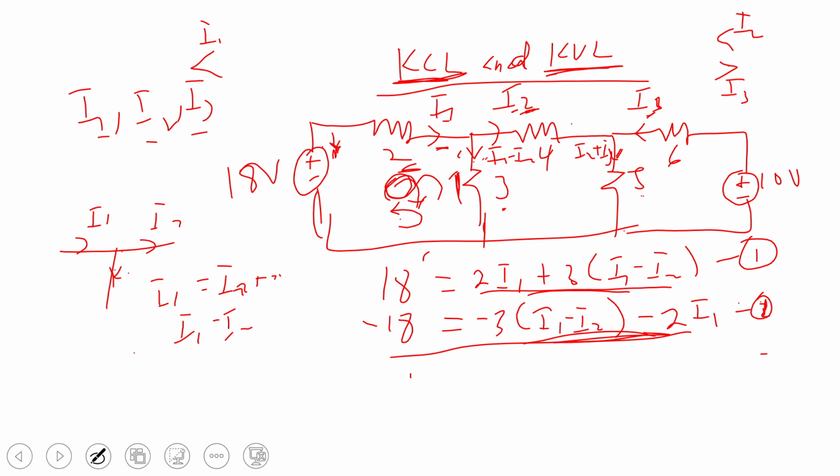So just decide the direction you want to take. But most of the time, what I decide is always to leave the positive terminal of the voltage so that I can avoid a lot of negatives. Or maybe when I look within the circuit and I see that the direction I'm picking, I'll get more positive things instead of more negative, then I'll take that direction.